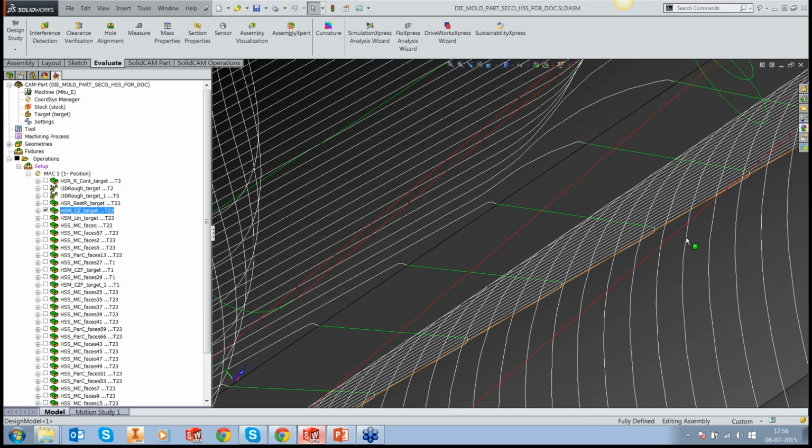Now, looking at the theoretical possibility, there's absolutely no way you could actually end up getting those lines that I showed you in the photograph. But we need to be a bit pragmatic. We need to be realistic that the tool here, even though it's lifting up, is still loaded. So as soon as it is released from that wall, it tries to go back to its original shape.